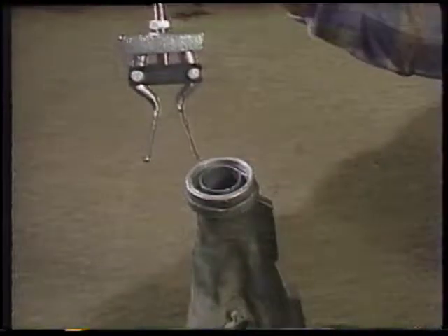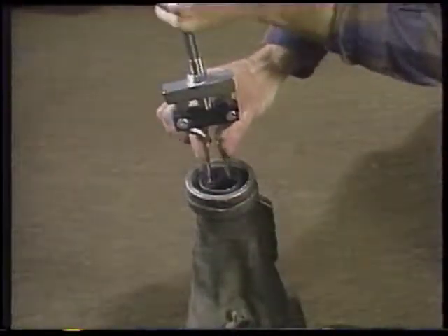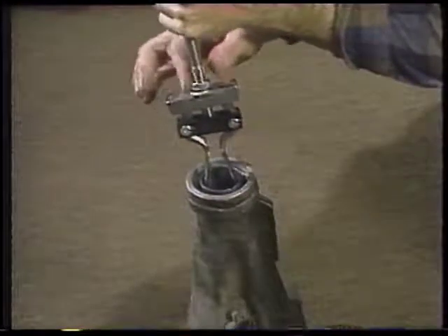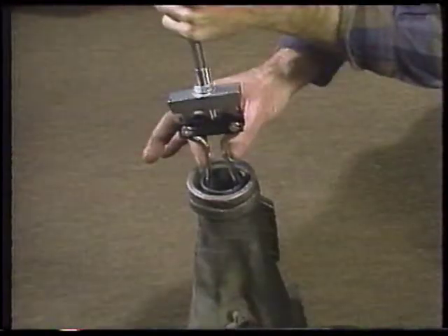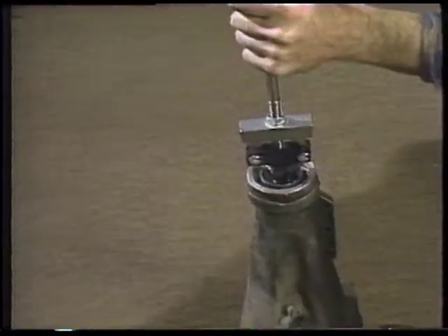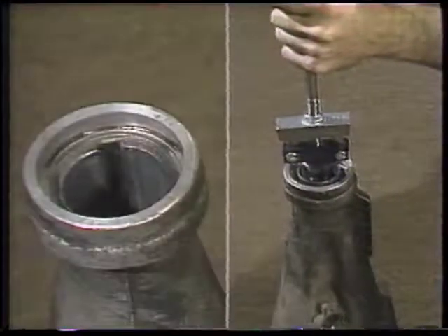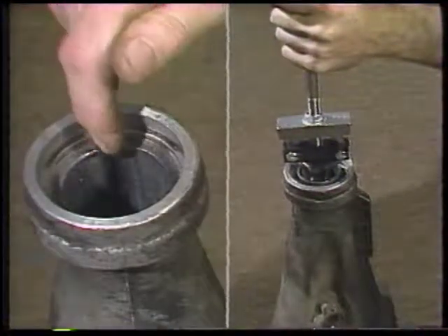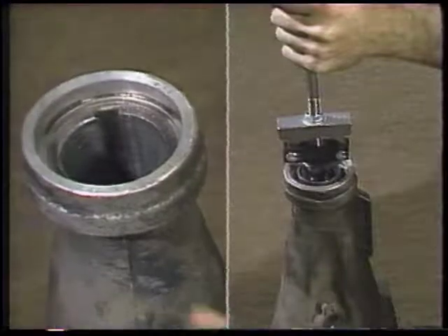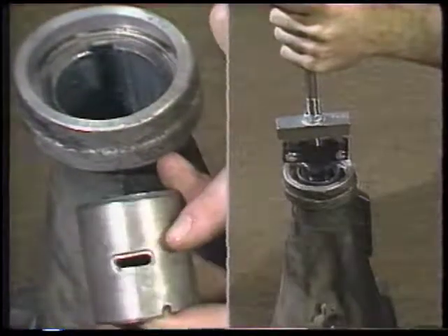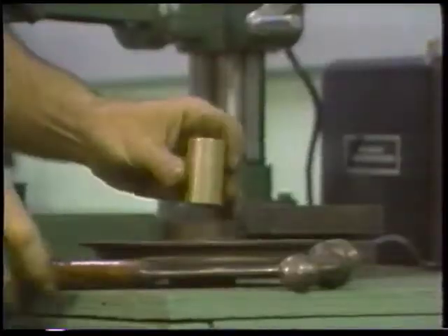This kind of damage can occur when removing an old bearing. For example, if not used correctly, the hooks on a bearing puller can scratch the bore. Before installing a new bearing, check to see if it has grooves or slots for oil or grease, and that any feed holes for lubrication are clear and clean, and that they line up correctly.